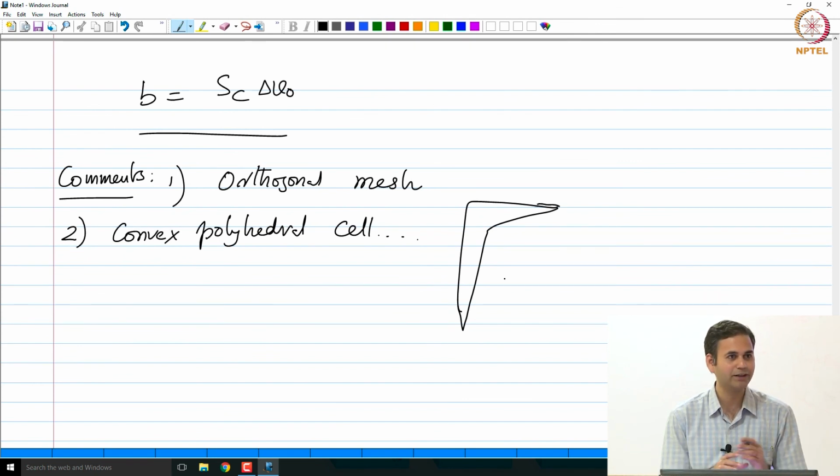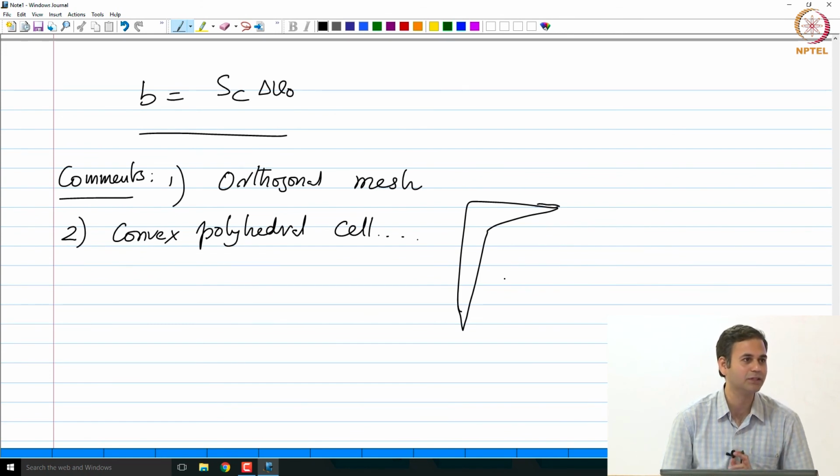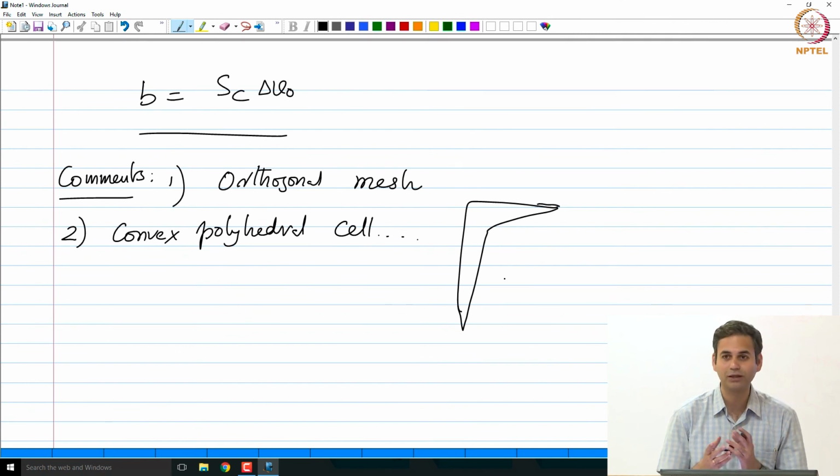somehow I have generated an orthogonal mesh. So, we have a boomerang like this, which can give us some kind of an orthogonal mesh. Cell center will be outside, so what? We do not care why the cell centroid is outside; what is the problem? Essentially, it is not a representative of the cell values. What else can go wrong?